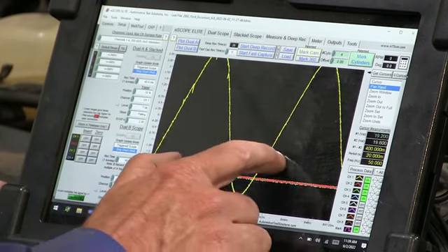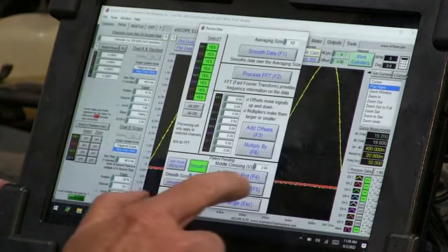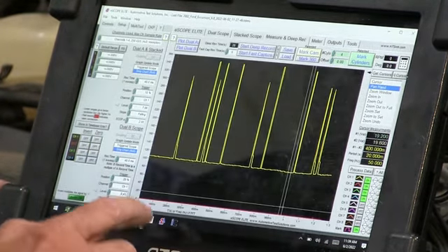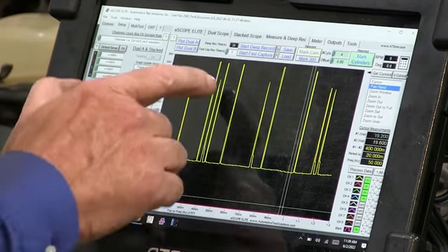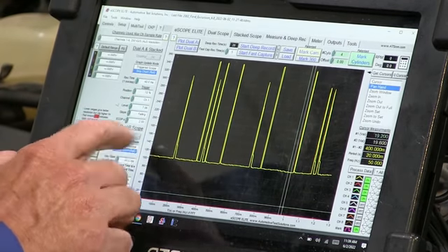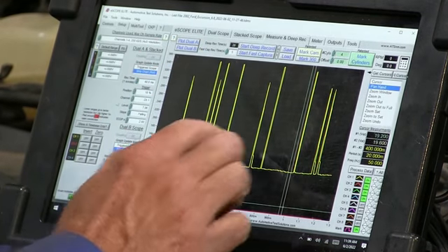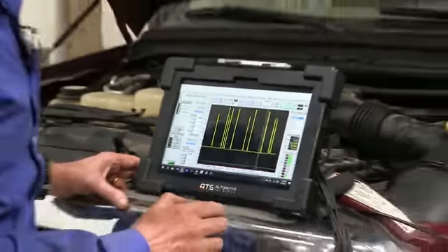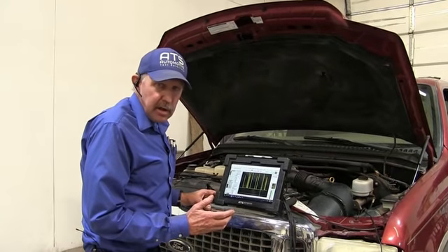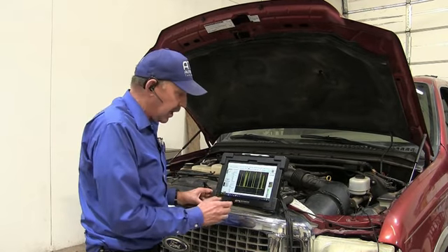Those are ignition spikes, guys. Let's go ahead and run the frequency plot. That's what the computer's saying, because it's counting edges. It's saying the shaft speed is all of a sudden way elevated. Now this isn't the sensor breaking down. This is not the sensor. This is ignition noise riding on the signal.